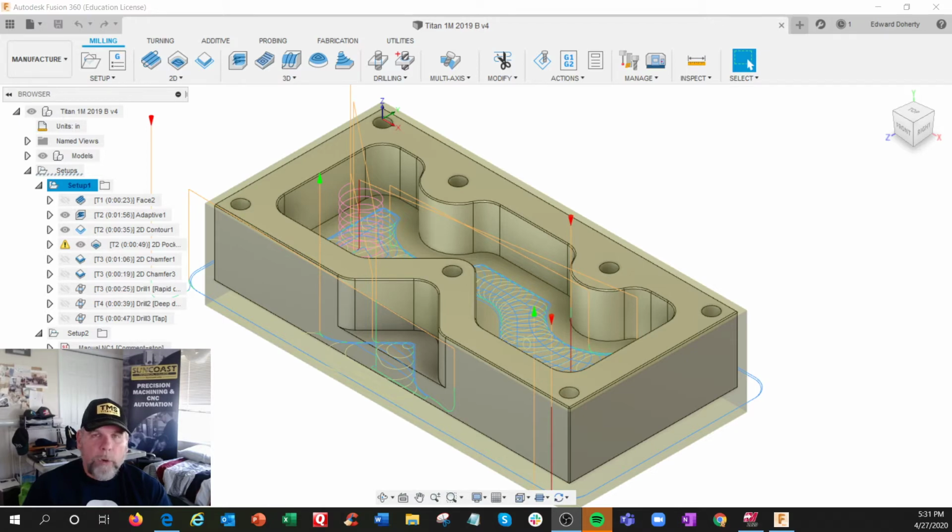Just doing a quick video about shortening your programs in the CAD/CAM system so they'll fit in your Haas machine. We have the same problem at our school. We have a 1 megabyte capacity, and a lot of it is occupied by the Renishaw probing programs, so we end up running off the USB a lot in FNC mode. If you bump the USB or pull it out, or if there's a blip in the power, you might get a little hesitation and lose some functionality.